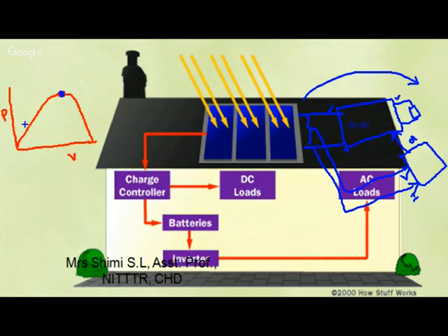Now what will we do? Say that voltage and current is this. Just think कि इस point में मेरा voltage ये था और मेरा current ये था। Okay? So now what I am doing? Is this my maximum point? No. So what I'll do? I'll change the duty cycle of this buck boost converter and again note what is my voltage and current. So my new voltage and current is this. Okay? So let me keep that as V1 and I1.